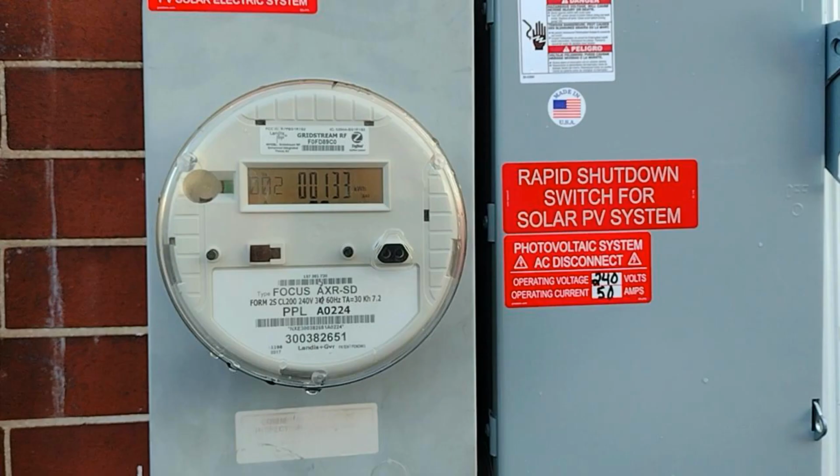Okay, window number 2. This is your lifetime return meter. This also is like an odometer that never resets, always goes up, never goes down, but instead of reading the power going to your building, this is reading the power that's coming from your building back onto the grid. If you have a solar or a wind generator, this isn't how much power you've generated.